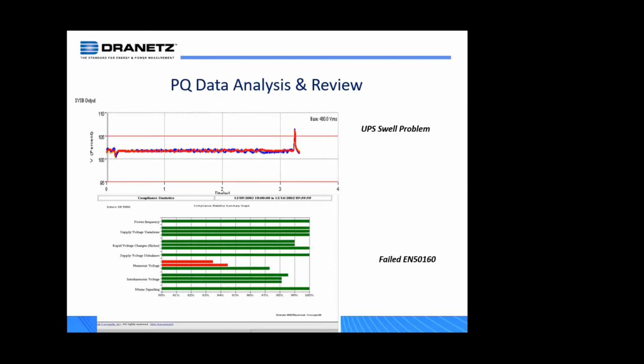Number one, you want to make sure that the UPS is doing what it's designed for, and that's protecting the sensitive loads from variations on its input. So you're doing that. Number two, because you're monitoring the input of the UPS, you're monitoring what the utility is doing, how many disturbances and faults you're getting from the utility.